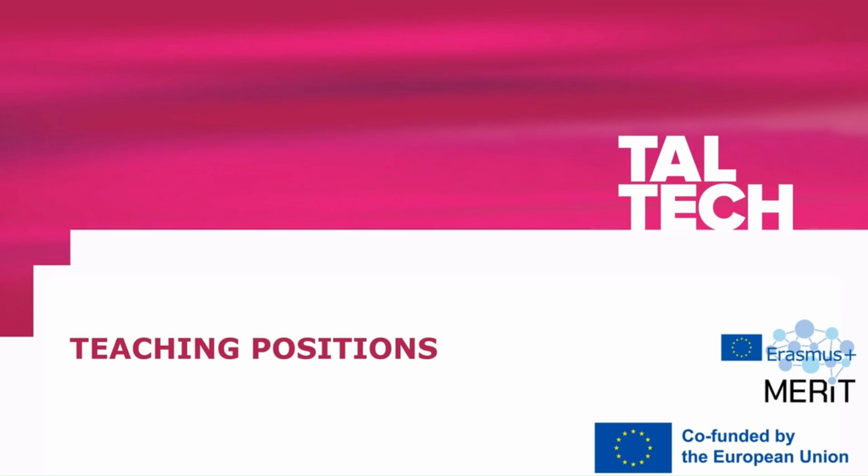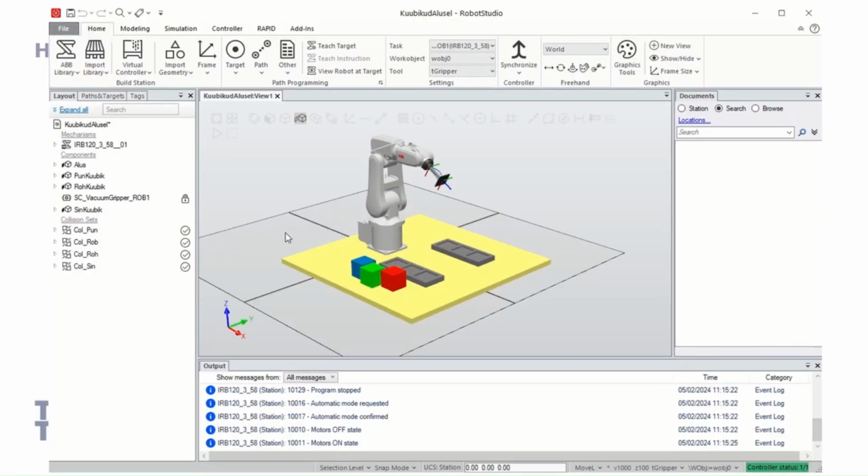Now we start with the position teaching in ABB RobotStudio. First, we start with the home neutral position on the robot part. At the moment, you can see that this is the initial state of the robot, and we don't like it because the gripper, or let's say the vacuum gripper, is not oriented as we need.